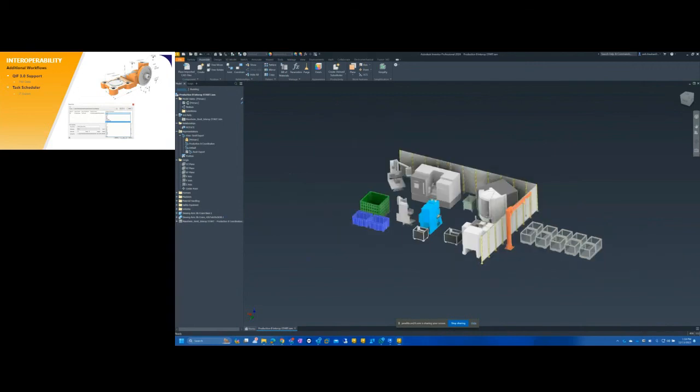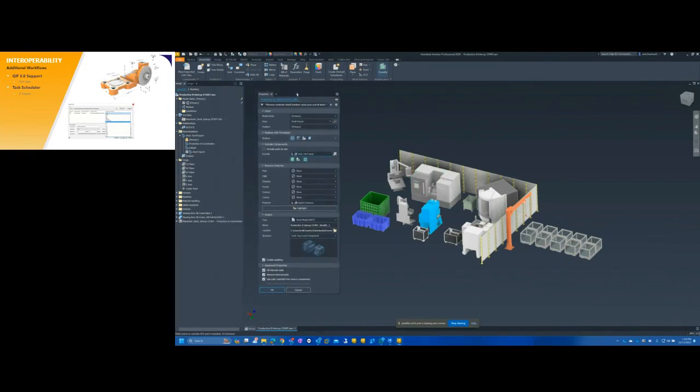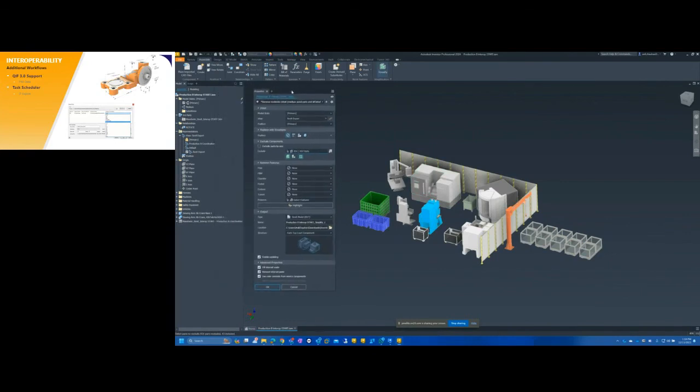And so to simplify this down within Inventor, I'm going to use my simplify command. My simplify command is going to allow me to simplify this model down and get it prepared to bring into Revit. And so you can see I've got a few different things inside of this simplify command that I can control. So you can see that I can replace with envelopes, right?